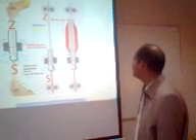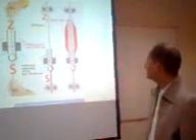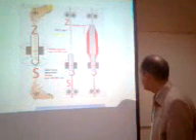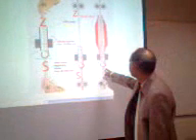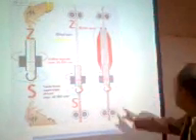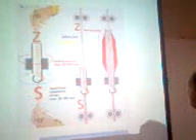Here you can see the hollow spindle spinning system. In the hollow spindle spinning system, the twist is inserted by a twisting hook, and the main yarn comes from the drafting system, then enters the tube of the hollow spindle, which is twisted on the lower side with a twisting hook, and after twisting, the yarn is delivered.